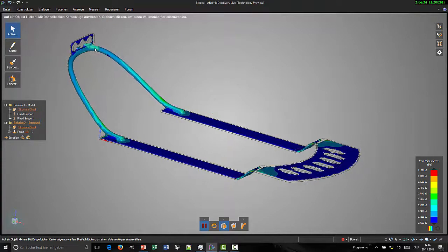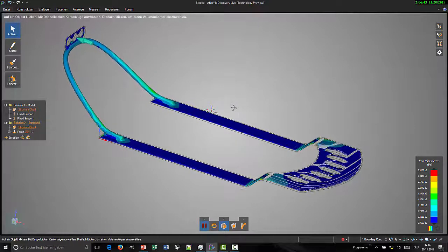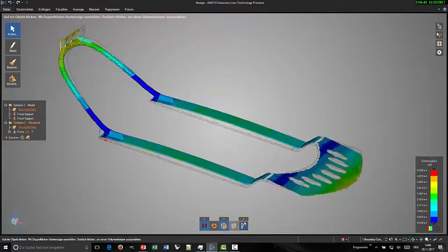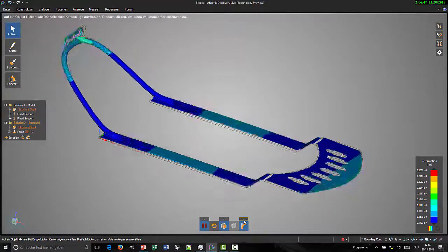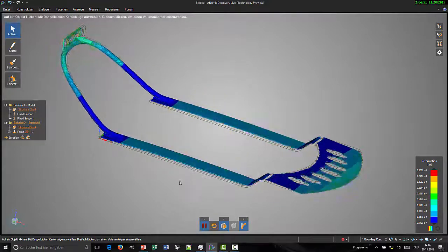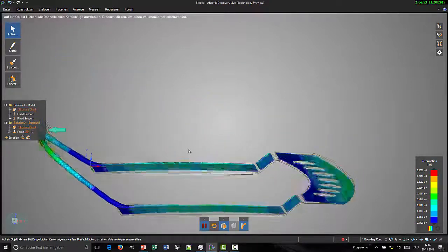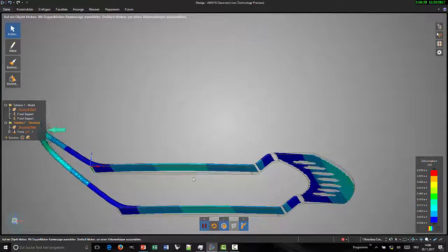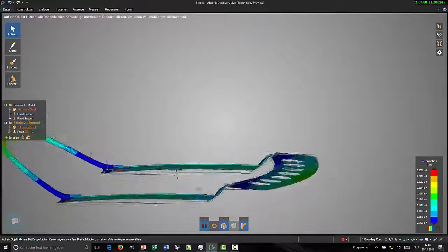So I increase a bit here the value so that you can actually see something. You have to press enter, and also you can hit, I will do it now, hit here again the simulation button, so you see how your structure deforms under this boundary condition, this load boundary condition. And the same like before, you can interactively select faces and assign new boundary conditions.